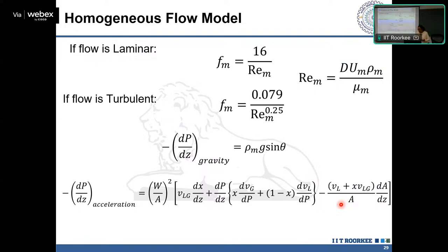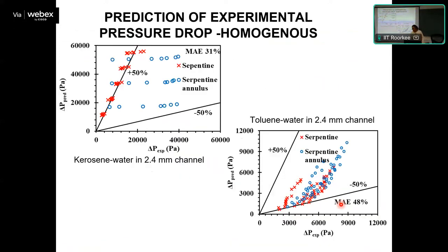In most cases, if you are dealing with no change of pressure, no change of phases and a straight tube, then this equation becomes simpler. Further, you have friction and gravity only to calculate, and mostly it is the frictional one that we estimate. So this model has been developed for macro geometries, working perfectly fine for bubbly, dispersed flow in macro geometries.